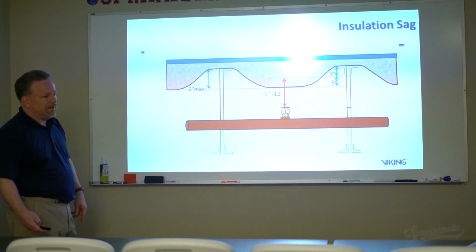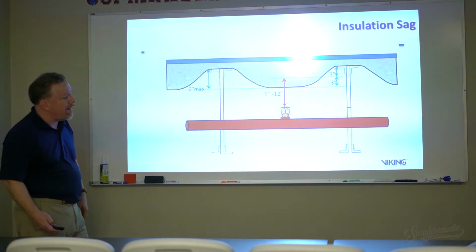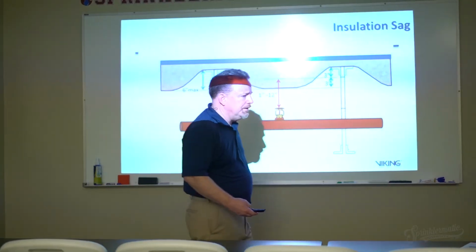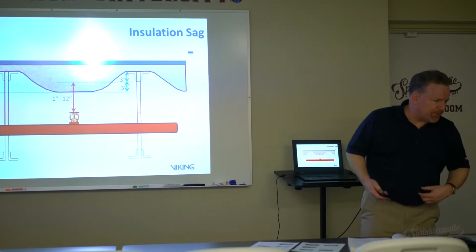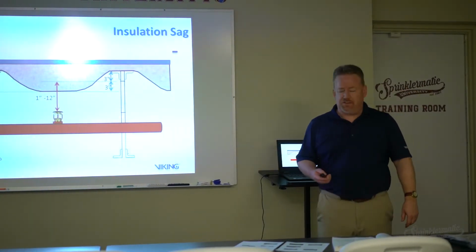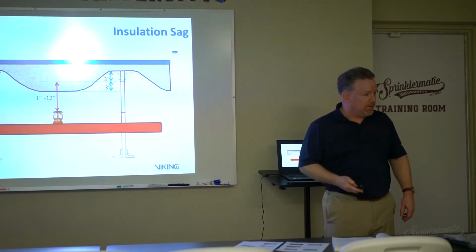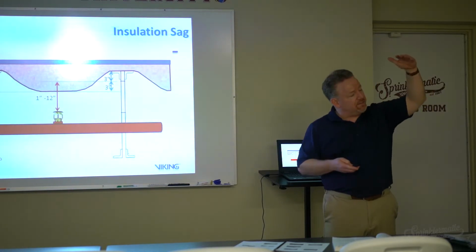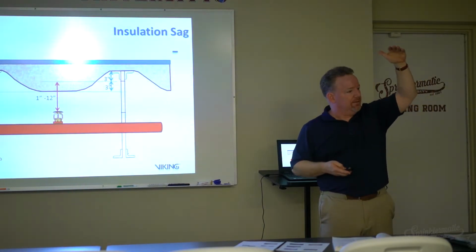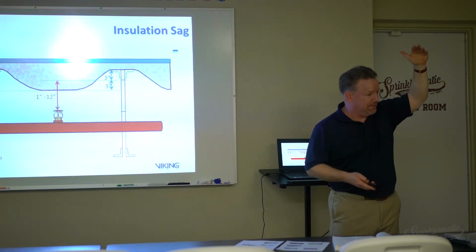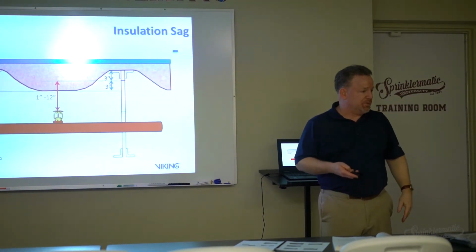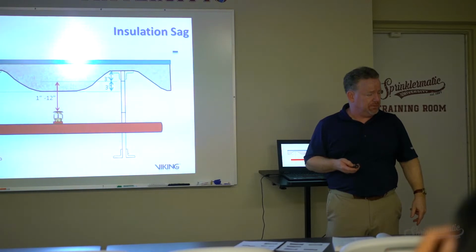Closer to 24 inches. Pardon? Sprinklers closer to 24 inches. 24 inches where? From the ceiling. 24-inch gap from the ceiling. There's got to be a 24-inch gap between that and the ceiling? No, it's not 24, but it doesn't have to be. Okay, that's what I'm saying. There's a maximum that it can be in some cases. Flat smooth ceilings, I think, are 22.